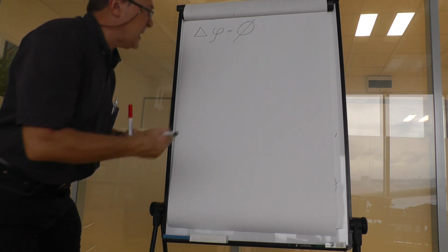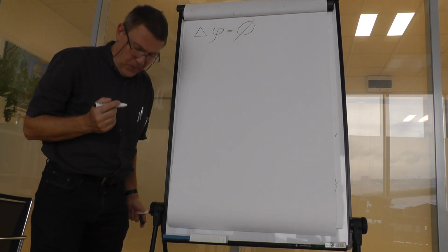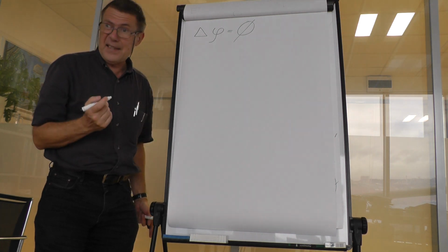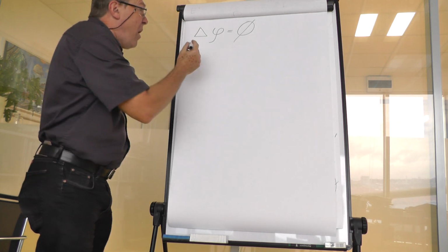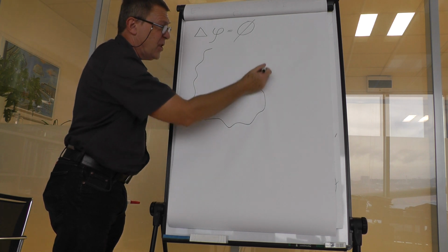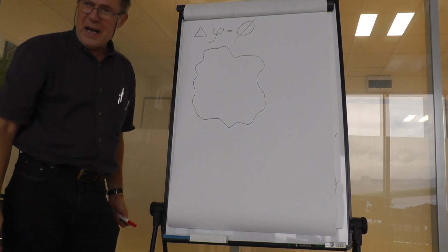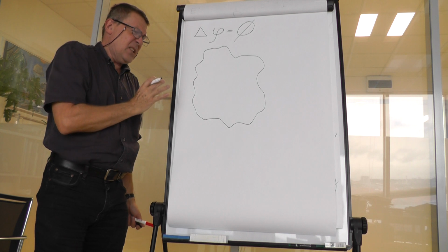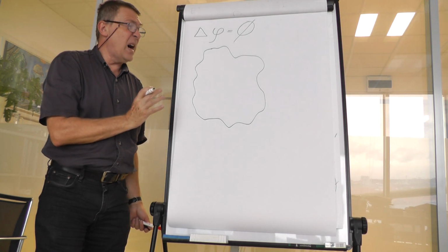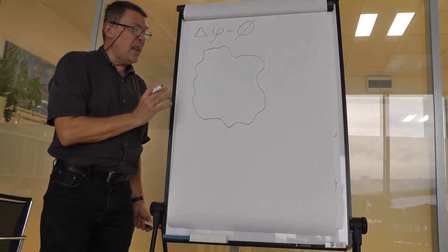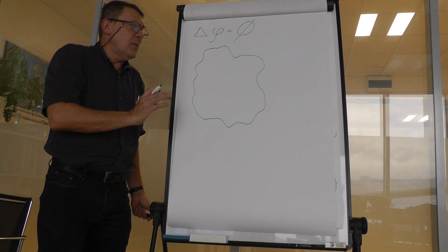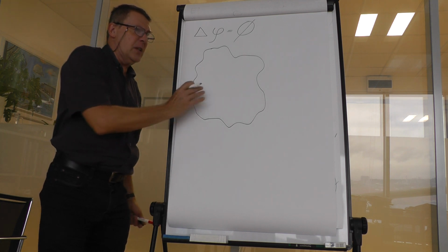The first method is called the method of finite differences, or a method of nets. How does that work? Let's say we have an area within which we need to calculate the electromagnetic field. And as you can see, it's not very regularly shaped. Now, in order to find the field, we would have to give up establishing a function that would describe everything.